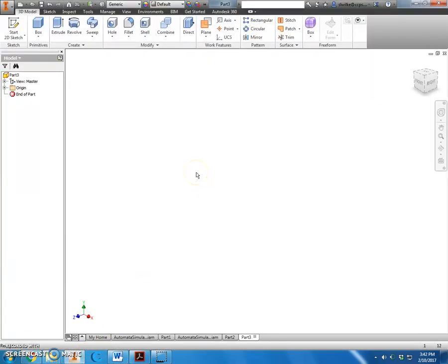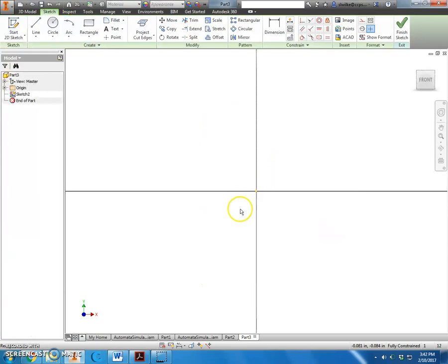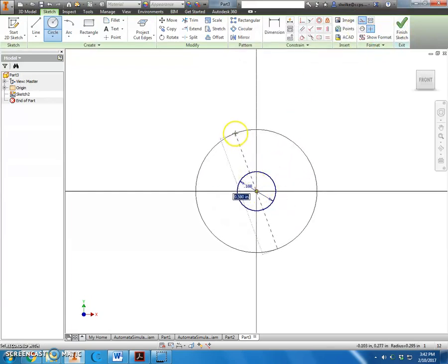Now, to make the SnailCam, first thing you're going to want to do is make a new part file. You're going to select a plane that you're going to be drawing on, and then the first thing we're going to draw is actually our axle hole, so that's 3/16 of an inch. You can actually type it as a fraction and it will calculate that math for you. I'm going to switch from regular lines to construction lines, and that's found over towards the end in the Format panel. And I'm going to make 2 circles.